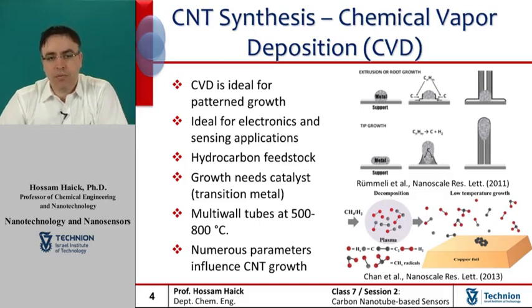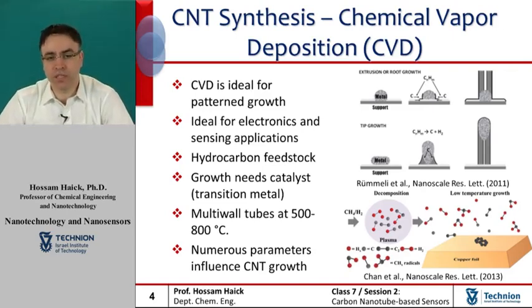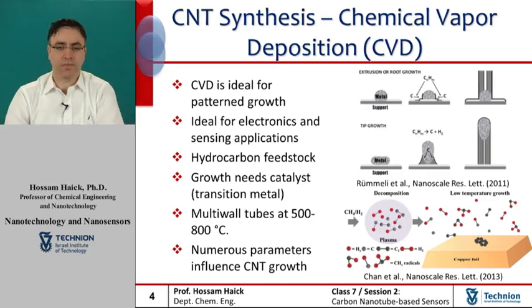Excess carbon buildup occurs at the exposed particle phase and is transported by the surface diffusion around the peripheral surfaces of the particle to form an outer skin on the filament.